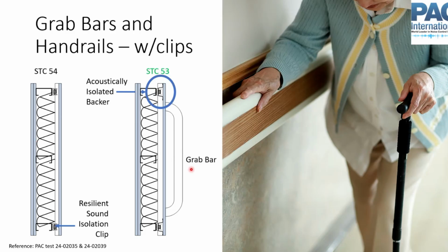And so for all of these, whenever you're looking at these details, if you can get acoustical test data, and you can get sort of an A/B comparison of with and without, whatever the acoustical product is, or whatever the detail is of mounting a cabinet to a wall, and you can get back-to-back tests in the same lab, same construction, and all of these kinds of things, that's the most informative way of looking at this, to see what effect these things have.